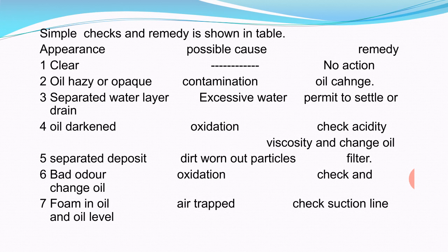Bad odor: the cause is oxidation, and the remedy is to check and change the oil. Then seventh, foam in oil and oil level: air may have been trapped, so check the suction line. This is only a 5 marks question, so you can name some of the problems and remedies here.